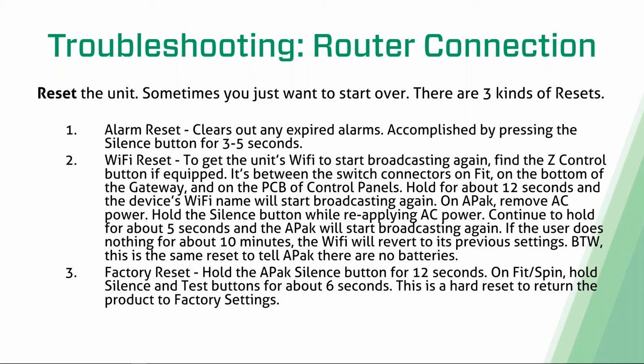First one we're not really talking about here. That's just an alarm. So if there's an alarm and you press the silence button once and let go, that's silence. If you press it and hold it for a few seconds, that's a reset. So you're clearing the alarm out of the device.